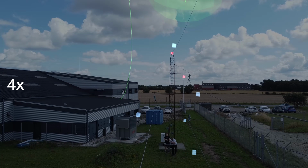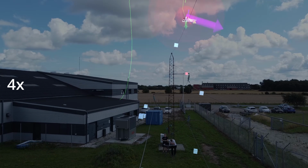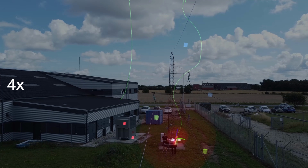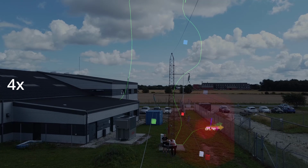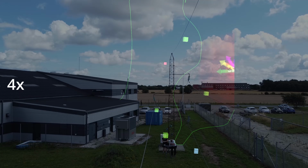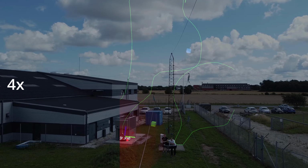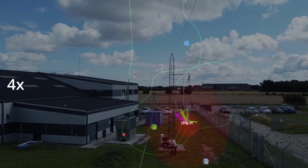This sped-up test shows the radar detections generated in a power line environment, as well as the outputs of the collision avoidance algorithm. When radar detections are made within the large red avoidance sphere around the UAV, the desired input velocity is corrected based on the tangents to the detections in the sphere.